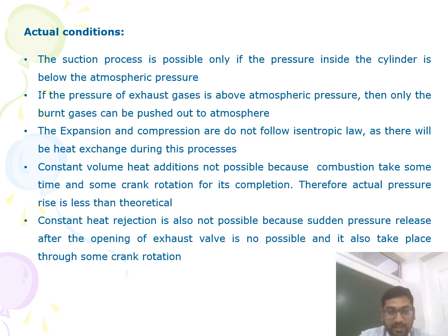The second condition is that the pressure of the exhaust gas must be above atmospheric pressure; only then will the burnt gases sweep out to the atmosphere. As I said earlier, at the end of the exhaust stroke, the pressure inside the cylinder must be higher than atmospheric pressure, so that all the burnt gases sweep out to the atmosphere. Third condition: the expansion and compression do not follow any isentropic law.